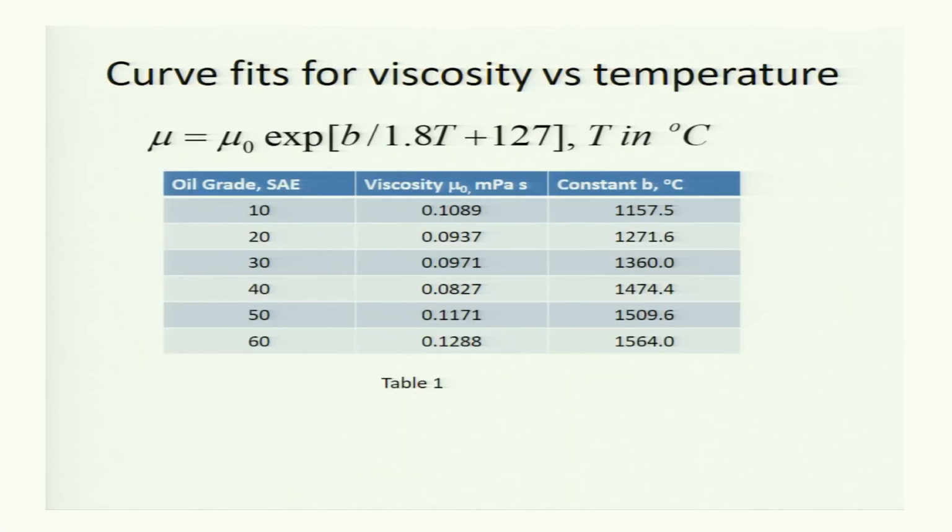Now, curve fits for viscosity versus temperature are also available. You may get the value of mu corresponding to any temperature in degree centigrade by getting the value of mu 0 and this B from this table corresponding to different grades of the oils.